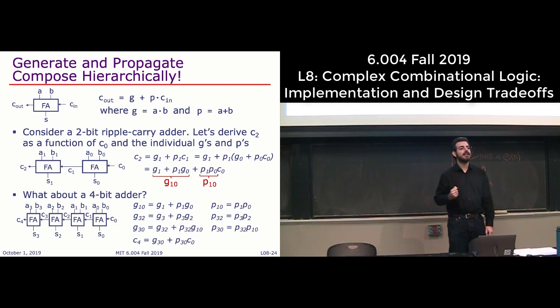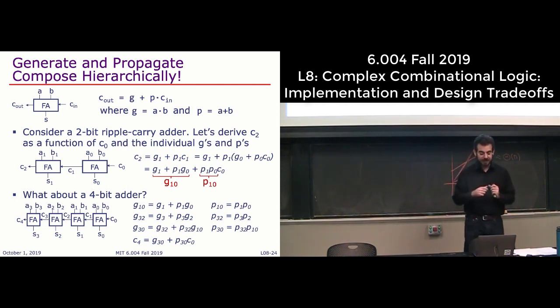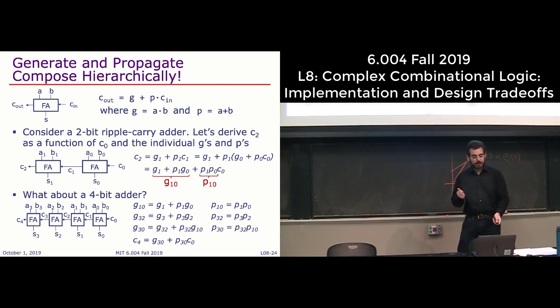And now the key step here is, do I need to do these two serially? Do they depend on each other? No, they're parallel. So I can implement this as a tree. And once you understand this basic fact, and we'll see this in recitation tomorrow a little bit more, you can build the whole family of carry look-ahead adders. But this is the key insight: by reassociating things in terms of propagate and generate signals, you can build trees of generate and propagate signals that let you derive these very far away carries in a logarithmic number of steps.